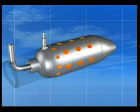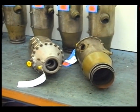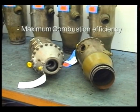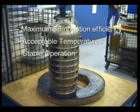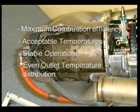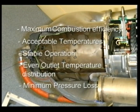The function of the combustion chamber is to burn a mixture of air and fuel at a steady rate and produce a continuous steady stream of gas at a uniform temperature. The requirements of a combustion chamber are maximum combustion efficiency, acceptable temperatures, stable operation, even outlet temperature distribution, minimum pressure loss.